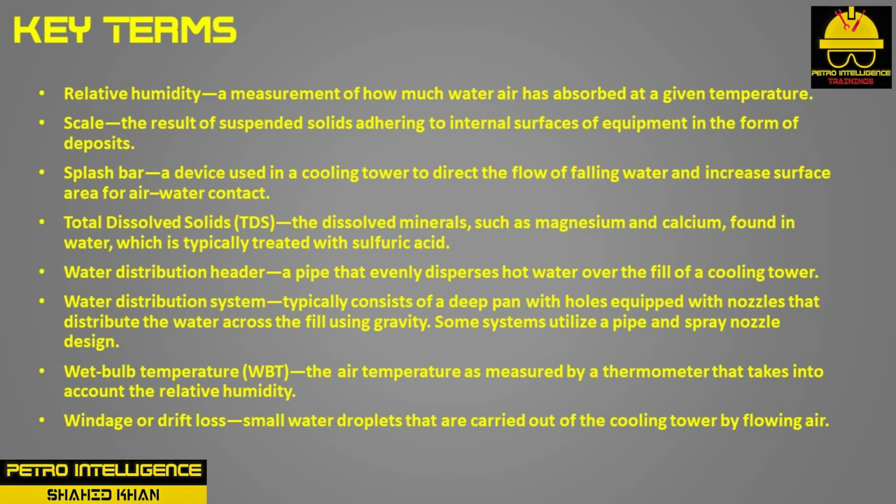Scale is the result of suspended solids adhering to internal surfaces of equipment in the form of deposits. Splash bar is a device used in a cooling tower to direct the flow of falling water and increase surface area for air-water contact. Total dissolved solids, TDS, are the dissolved minerals, such as magnesium and calcium, found in water, which is typically treated with sulfuric acid.